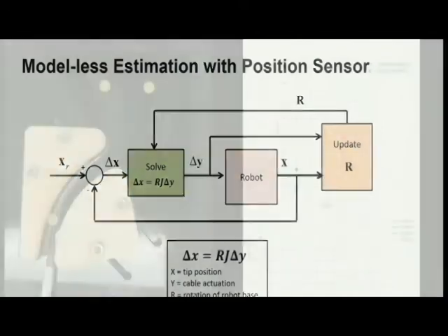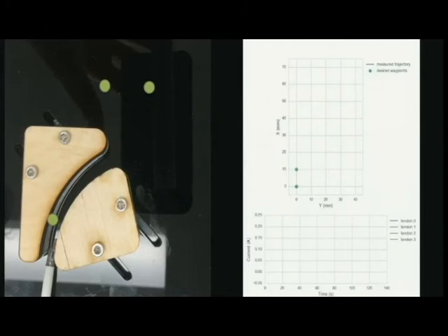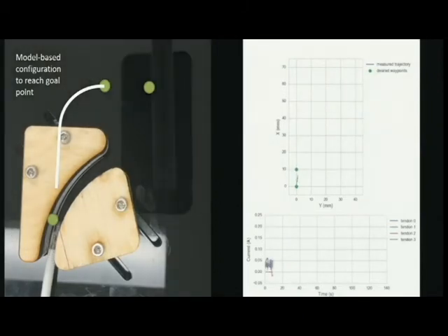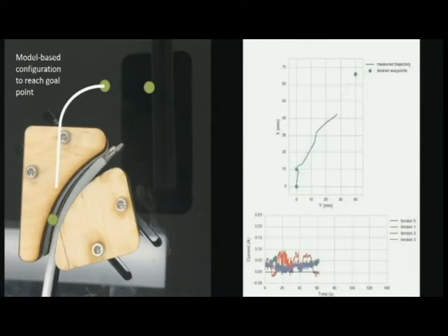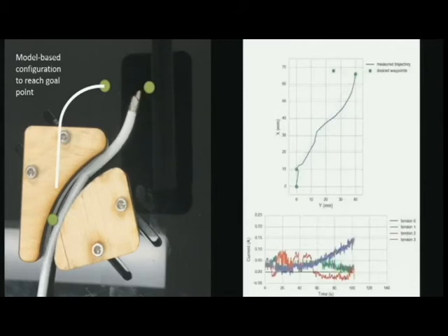So how does this work in practice? Okay, so we have a few waypoints here that we're trying to follow, and it goes from, let's see, from this one to that one to this one. If you simply use the mechanics model based approach that I first told you about, it would think you just need to go up and turn over to the right. But if you follow these waypoints and you start to run into these obstacles, of course you learn as you're going that you need to in fact move back to the left.